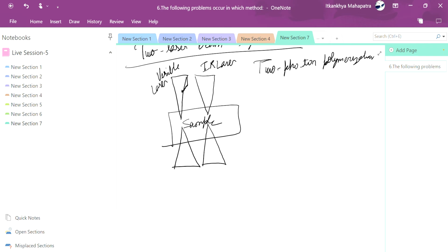So what happens is when one laser excites molecules all along its path in the vat, then most of these molecules will return back to their unexcited state after a short time. Those also in the path of the second laser will be further excited to initiate the polymerization process. So on this basis, the resin cures at the point of intersection. This is the point of intersection of the two laser beams, while the rest, which are lying along either of the two paths, will remain liquid.